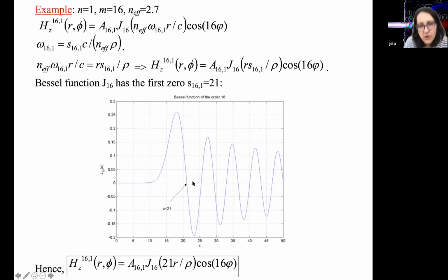We see a number of lobes that is given by your choice of the zero of the Bessel function where you're truncating. And that also tells you why we call the number n, which is the order of the zero which you pick in the Bessel function, the radial number. I said earlier on that radial number n means that you have n-1 zeros of the field in the radial direction. So if I truncate at the first zero, I will have no zeros, no intersections apart from the one at the very center, but we don't count that one.